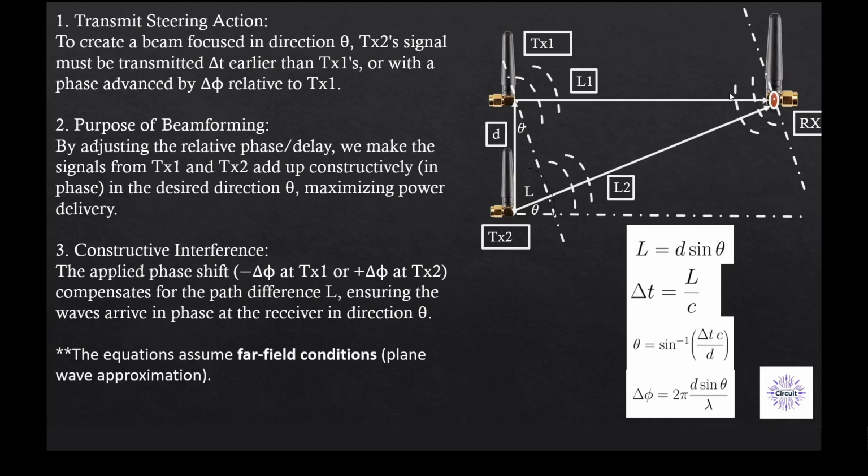For instance, we can use the idea of beamforming and also use multiple channels at RX to find out the arrival angle of the signal and other properties. But to not make this video long, we just want to explore the idea of having two TX channels and one RX channel, and see, if we change the phase between these two TX channels, what the received power is at the receiver.